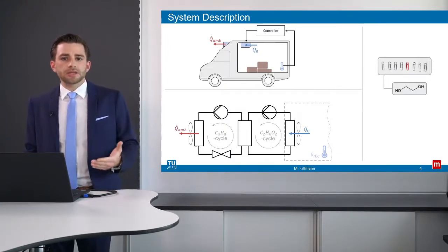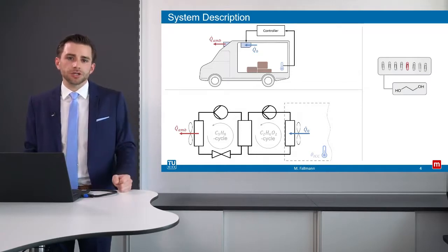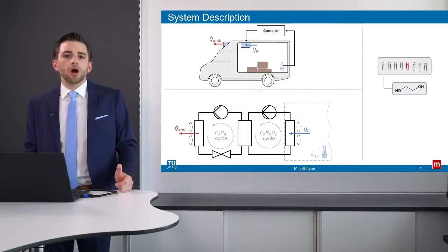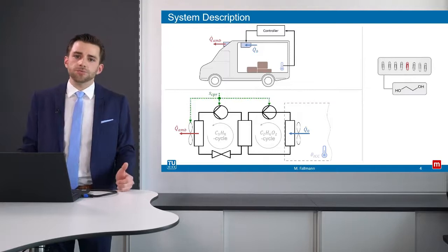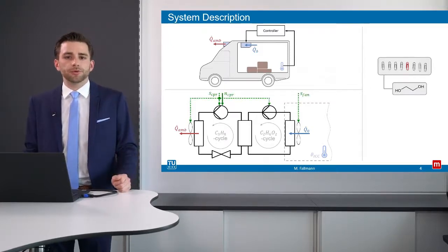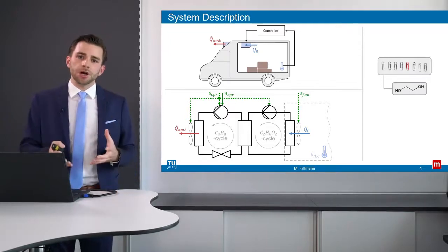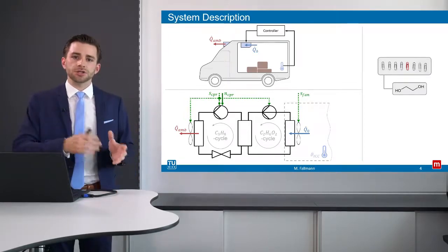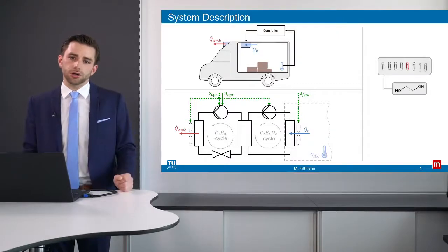One question remains, how can we control our cooling unit? The control inputs are the compressor switch, the compressor speed, and the air chiller fan switch in our project setup. So one can easily see now that we have to define continuous as well as binary logical control inputs.